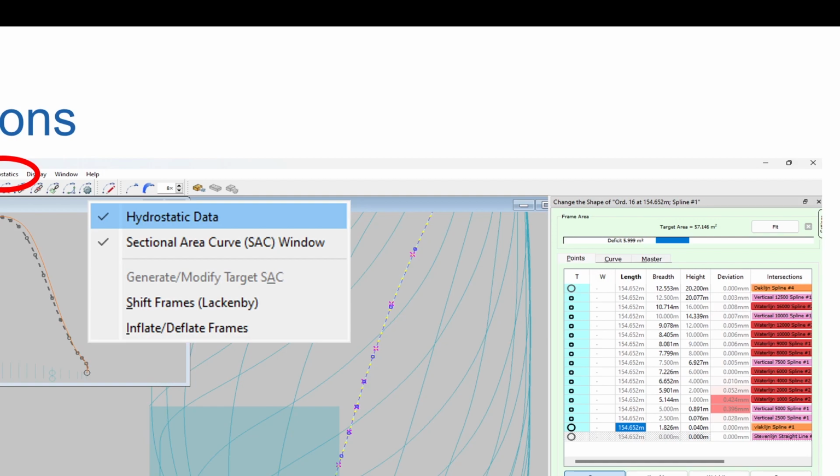Now, this is not what they call an affine transformation. So if you do this frame by frame, the rest of your model will look very ugly, of course, because you only did this on the frames and not on the waterlines and not on the buttocks in between. So you do this if you start designing with frames. If you have that, then you can fill in the waterlines and whatever. Otherwise, you'd end up with a nightmare of entangled waterlines and buttocks and what have you.